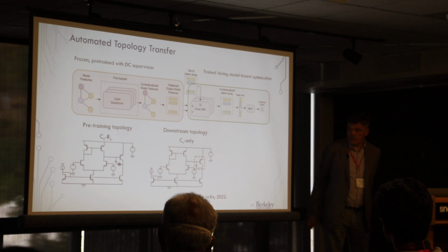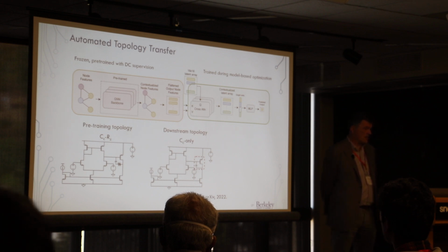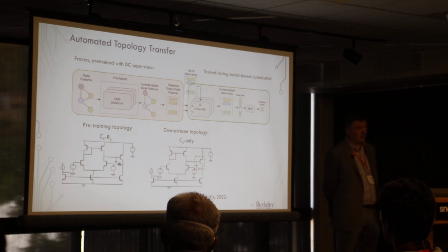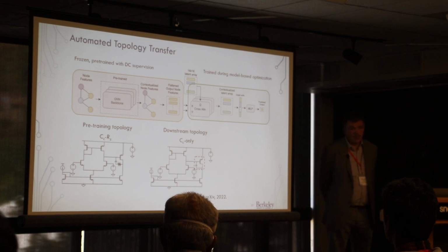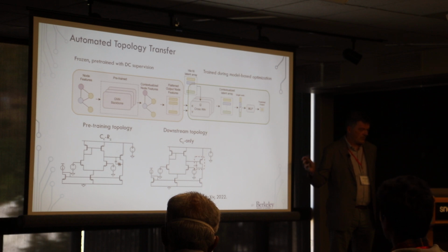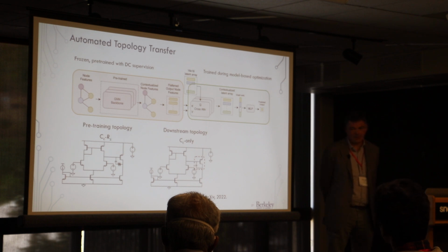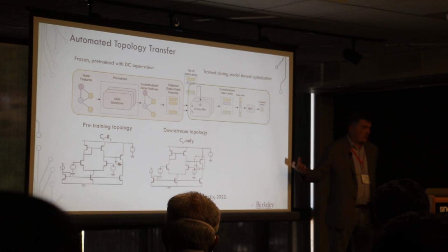And if you look at these 2 designs that are on the bottom, they're almost the same op-amps. One of them has just capacitive compensation, the other one has RC compensation to cancel the zero. This is something that is typically taught in classes, but topologically they're different. There are 2 different netlists, 2 different graphs corresponding to these two different circuits. I mean, you can still represent them in the same graph. You would have to have some kind of an impedance matched over there, but it is nominally a different topology.